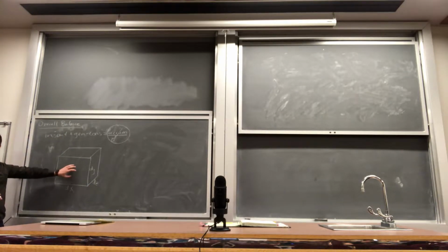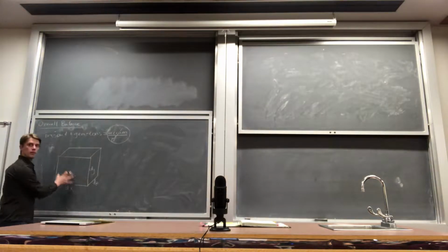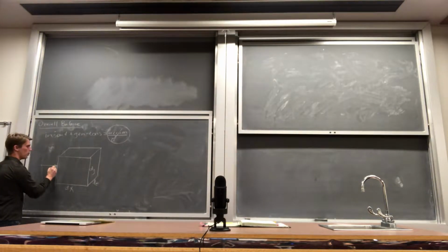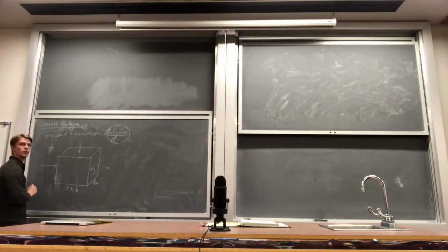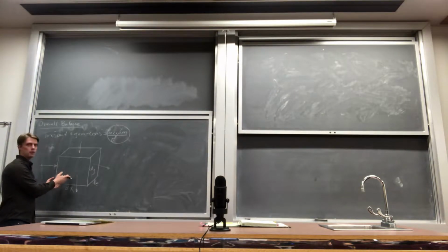We're not going to focus too much on the differential material balance, but this is really the future of your class curriculum, is transitioning from big unit, big chemical plant, to a small unit differential. So what's happening in this balance is that I have material flowing in and out from all different directions. And I'm going to keep track of how much mass or energy is stored within this differential element.